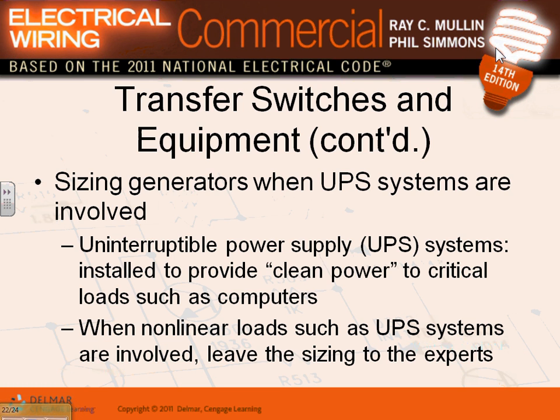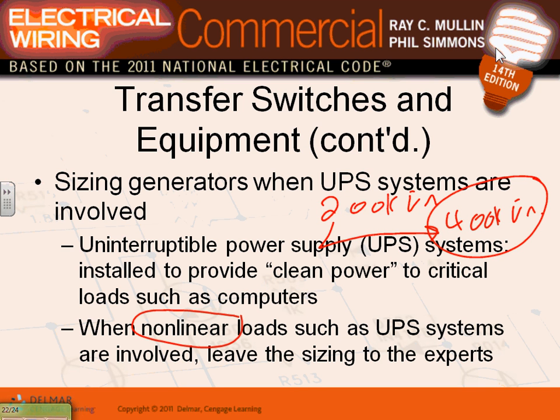A couple of things. Sizing generator. The last thing, guys, it talks about sizing a generator with UPS. It used to be the rule that if you have a nonlinear load like a UPS, you double the size. So if the whole load is say 200 kVA, when you size your generator, you multiply it by 2, that becomes 400 kVA, and you size your generator for running.